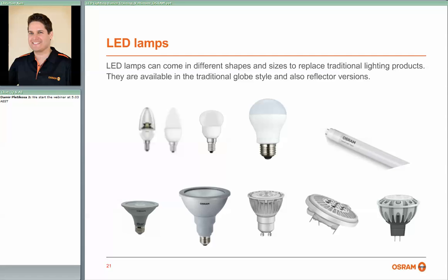Some of the cons also include what we talked about in the previous slide. So dimmer compatibility can be limited, particularly because the loads are behaving differently to the traditional technology. So, as always, make sure that the lamps are compatible with the dimmers you either have in place, or make sure that before you purchase dimmers, you purchase the correct ones for the product. We talked about this as well. For low voltage lamps, compatibility with transformers can sometimes be an issue.